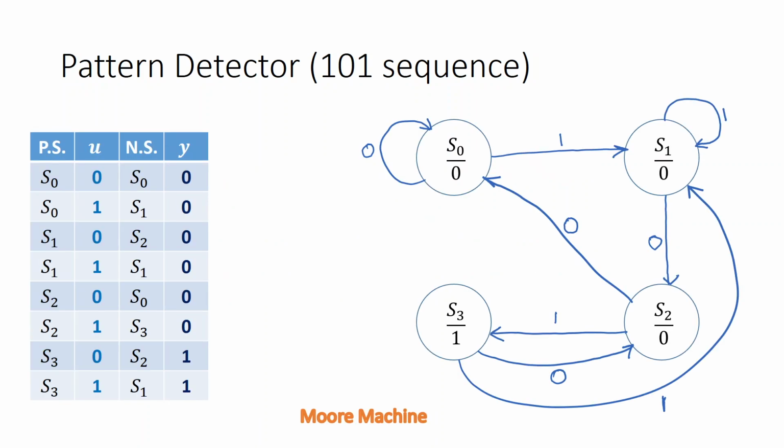The state diagram is drawn here, as per our sequence detection. So you just read the state diagram once. Let us look at it. S0 is the initial state, so we can give an arrow also here for the initial state. When we have a 0, we come back to S0, right? When you have a 0, we are not starting the sequence actually. When a 1 is detected, then we go to S1.